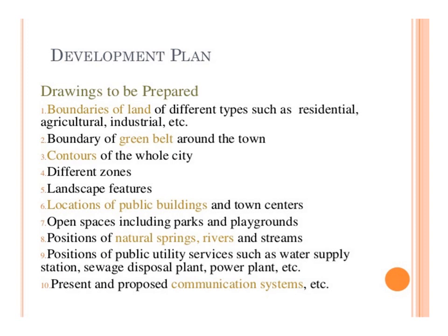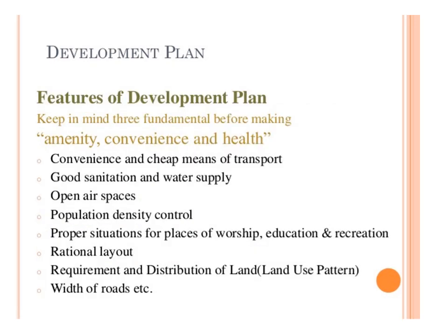public buildings and town centers should be highlighted, open spaces including parks and playgrounds should be shown, position of natural springs, rivers and streams are also highlighted, position of public utility services such as water supply station, sewage disposal plant, power plant, etc. are to be highlighted, and present and proposed communication system is to be shown in the development plan. Whenever the development plan is to be prepared, we are supposed to provide amenity, convenience and health.